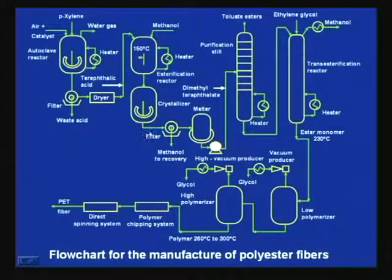So, DMT crystals are formed in methanol, and methanol is separated and sent to recovery, which can be recycled to this step. You see here, if some quantity of methanol is used at the beginning, the same methanol can be recycled for DMT manufacture.